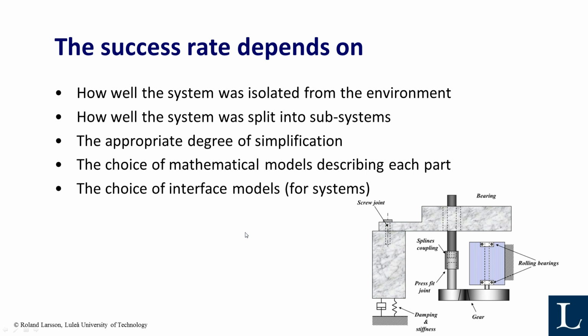That is maybe something new for many of you, but in this case we see it as very important. If we model a system like this, a machine system, we really need to model the interfaces in a good way. Interfaces here between the gears, in the bearings, in a coupling here, they are very important in order to model, for example, the dynamics of this system. The dynamics will strongly depend on the interfaces here, the function as well. So that's also very important.